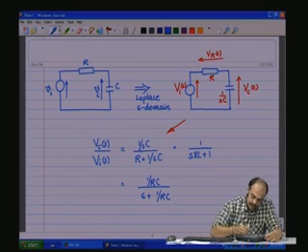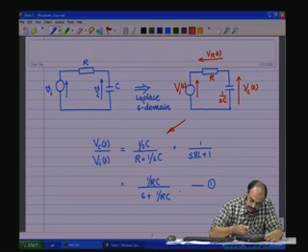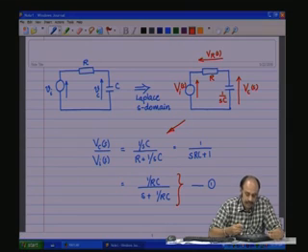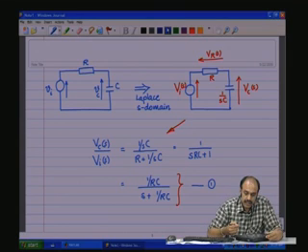This is one transfer function that we have obtained for the circuit, wherein the transfer function is basically in this case defined as the Laplace transform of the output variable Vc divided by the Laplace transform of the input variable Vi. But one need not look at the transfer function just as the output variable Vc by the input variable Vi.